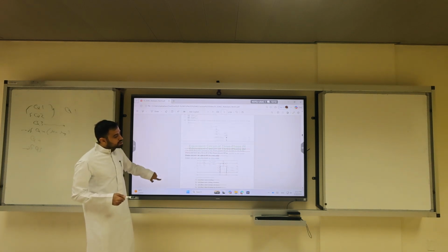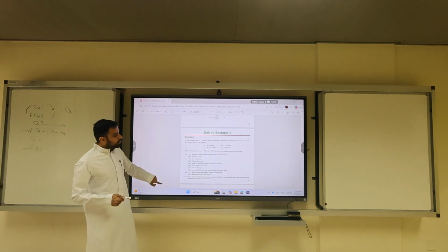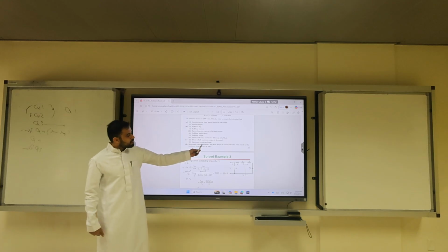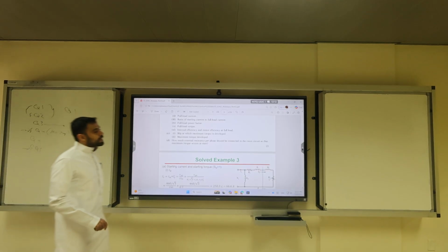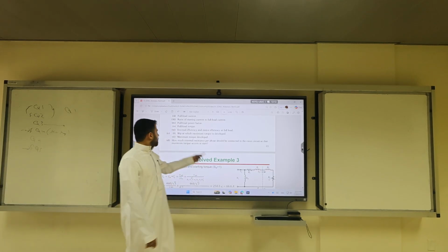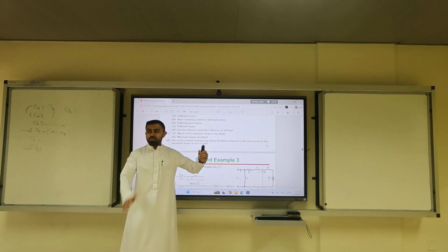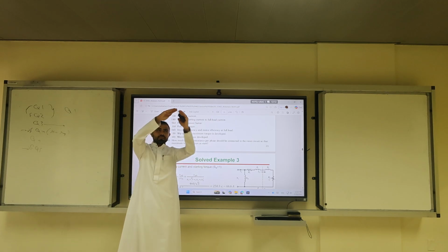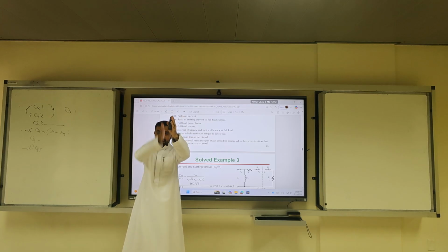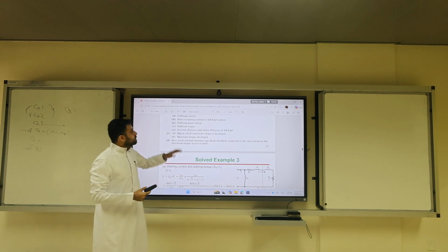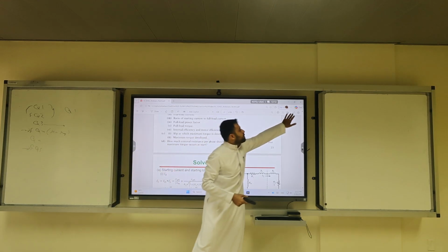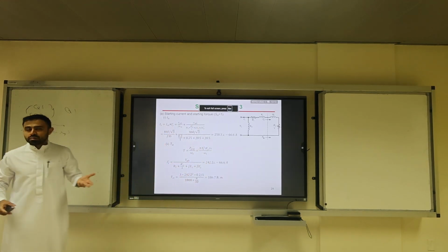Last lecture, what did we discover? We discovered in the previous example a very interesting idea. What was the idea? How much external resistance per phase should be connected in the rotor circuit so that the maximum torque occurs at start. So we shifted the maximum torque, instead of at slip max, all the way to slip 1, making it class D or C. Okay? This is the first idea of motor control.